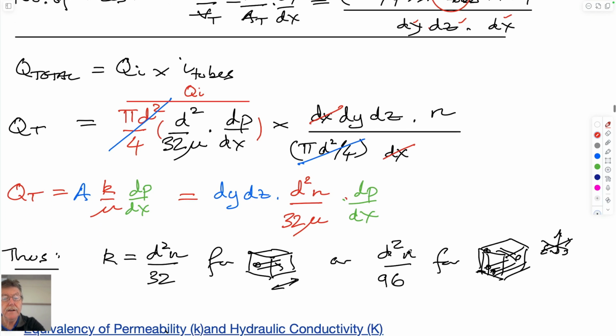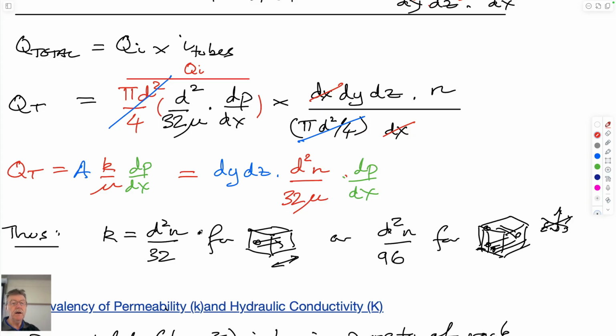And if we work those out, then we realize that any term that we get is a volumetric flow rate, which is an area, a permeability, viscosity, and a pressure gradient. So we just need to split up this expression in terms of those components. We get rid of the areas, top and bottom, and we're left just with this expression here.